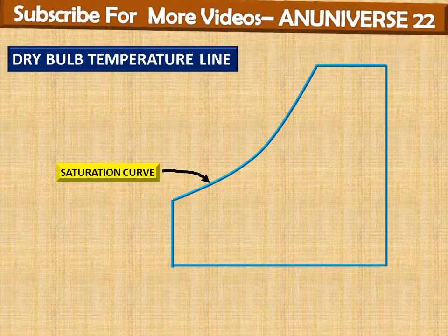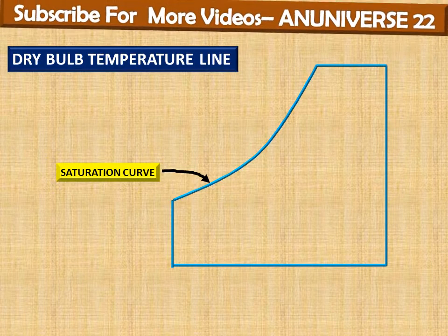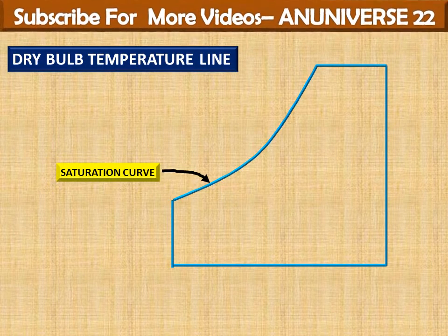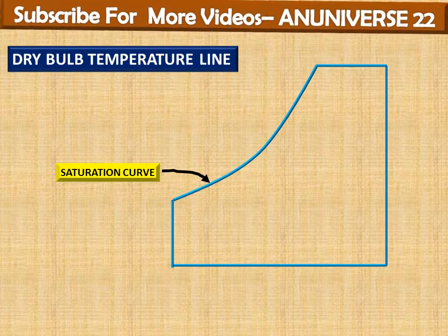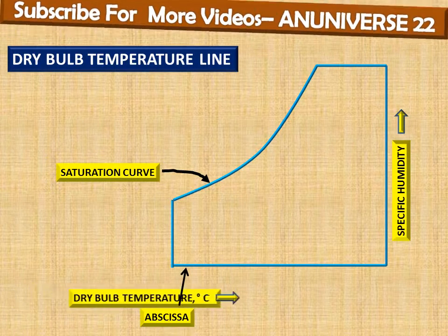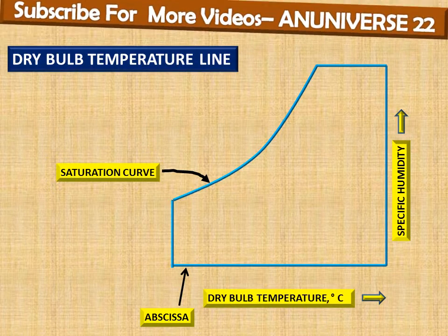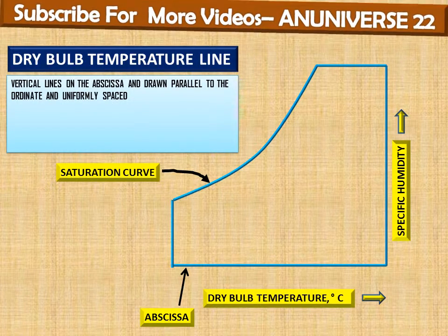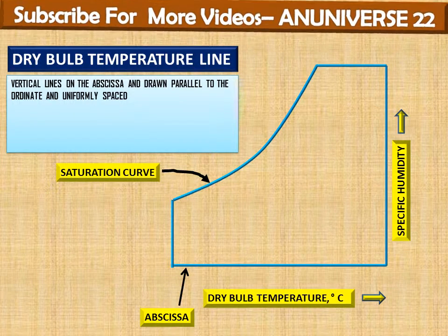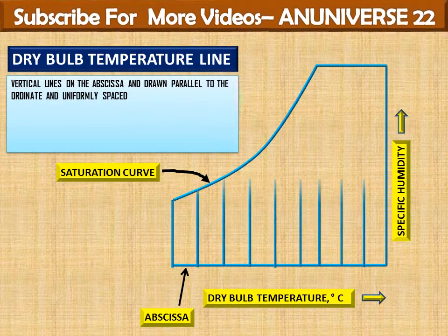It is a saturation curve, and dry bulb temperature is taken as abscissa and specific humidity is taken as ordinate. So on the ordinate here is the specific humidity, and on the abscissa is the dry bulb temperature. The dry bulb temperature lines are drawn parallel to the ordinate, and these are uniformly spaced.